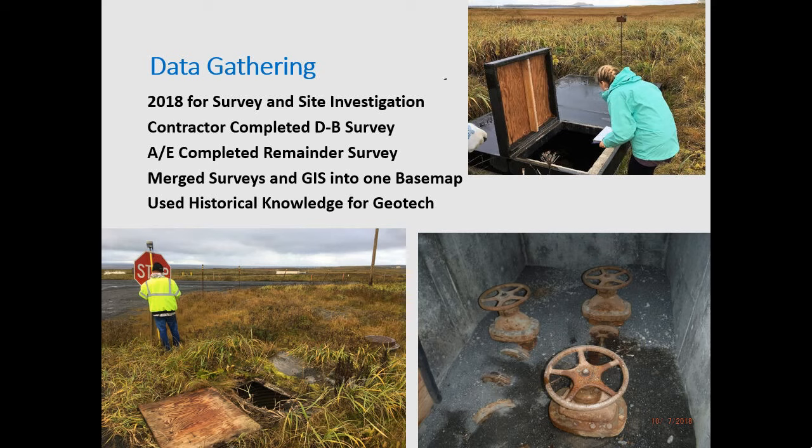And then we didn't do the geotech, and that was partly because of the cost of the mobilization. And again, all of the historical knowledge of what had been going on out at this facility for so many years. We had a really good idea what's going on with the soils, between the contaminated investigations, between all the projects, between the record drawings, the geo bores on all the stuff. We really had a pretty decent idea for the water that we didn't feel like we needed to gather that additional geotech. And so when the owner said that they didn't want us to do it, well, it was against our original recommendation. After talking through it and gathering that additional information, it was kind of like, you know what, you're right. We think we can have a pretty decent design without this additional information.